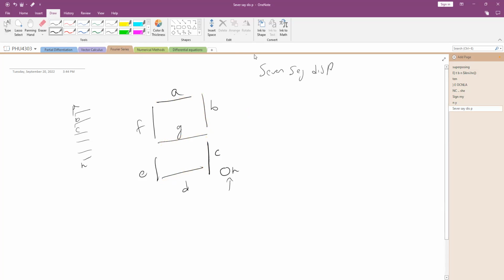So in this question, what I'm asking is, you have a binary number. The maximum you can go up to here is 9 in the decimal place, because you can't have a 10. To have a 10, you need another SSD, right? So you can go up to only 9. That means you can represent all the numbers that can be displayed in a single 7-segment display using only 4 bits. In 4 bits you can write 0, 1, 2 up to 15, but you don't go up to 15 here, you end up with 9.